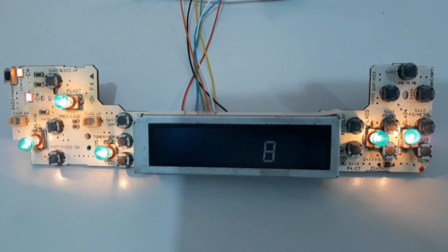So, the task of following the ways on the PCB becomes a little more complicated if you don't have the electrical diagram to avoid this. This panel belongs to a car radio from the brand ALPINE, and the model is the TDM7543M. There will certainly be other very similar models, so it is a tip if you stumble upon this type of panel to remember that we have to remove the LCD to see the reference of the driver.